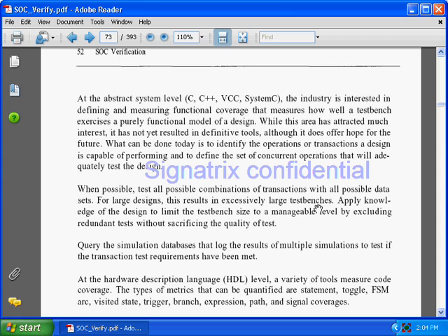What they are trying to say from this is, when you are checking the data, basically you have to send all ones, all zeros, or go with walking ones, walking zeros, with the 1010 sequence. Such type of data you can transfer when you are going with the data transactions. If an 8-bit data field is there, no need to specify all 2 raised to power 8 possible combinations. But in case of control information, during that time you have to check each and every bit. But in case of data, there is not much problem.